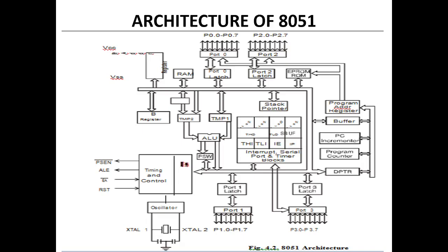The CPU is the brain of the microcontroller, reading the user's programs and executing the expected task as per the instructions stored in memory. It is the primary element in this microcontroller. The primary elements are the accumulator, B register, stack pointer, program counter, PSW and DPTR, and a few more 8-bit registers. First we see the accumulator.